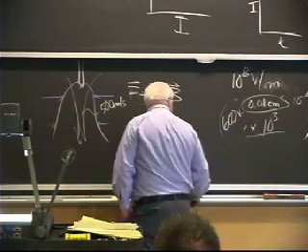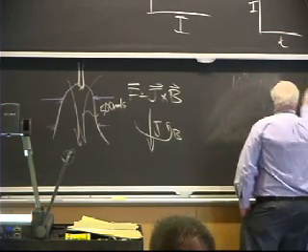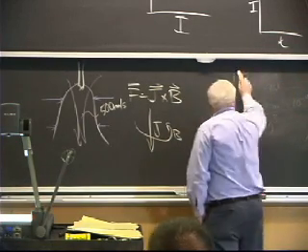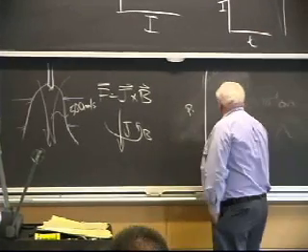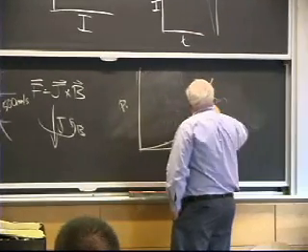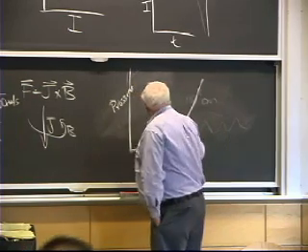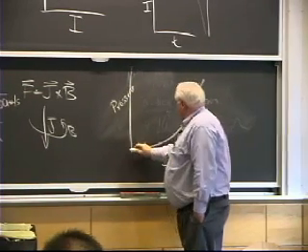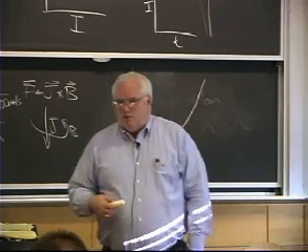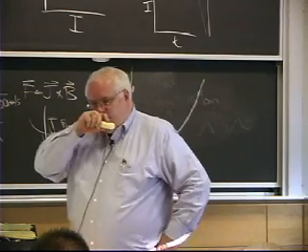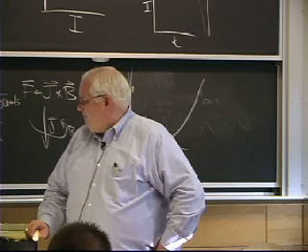And so as a result, if you were to plot the pressure of this jet hitting the surface versus current, you'll get a parabola that increases like that. So this is the arc pressure, and it can do several things. It can depress the weld pool surface. Remember I told you about how you depress the central artery. You have Michael Dukakis talk to it for an hour, right? That's where we finished up last time.